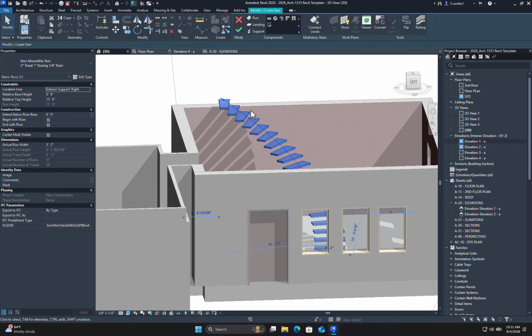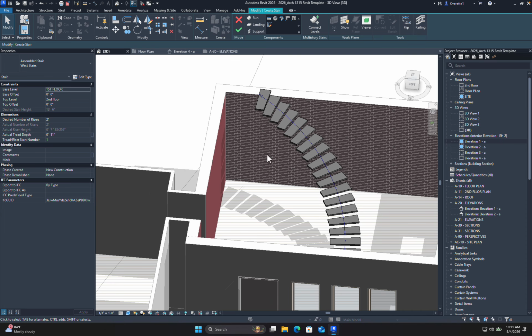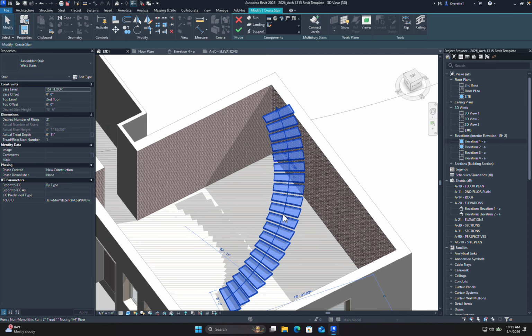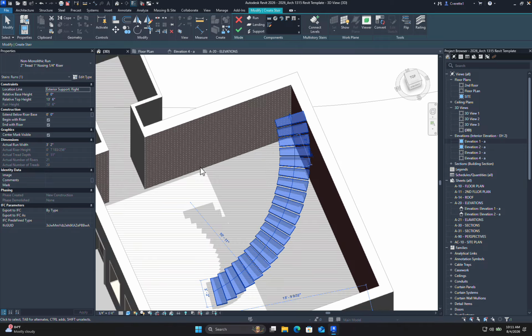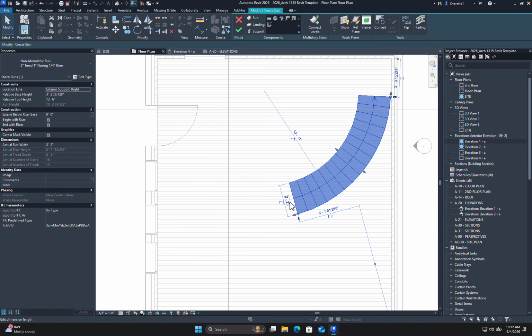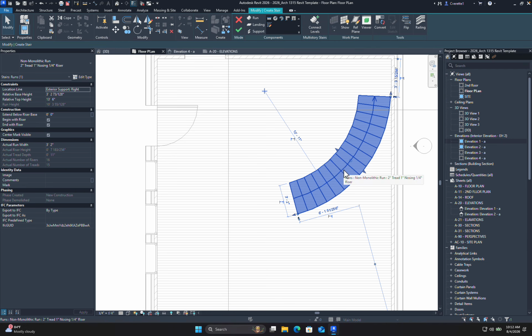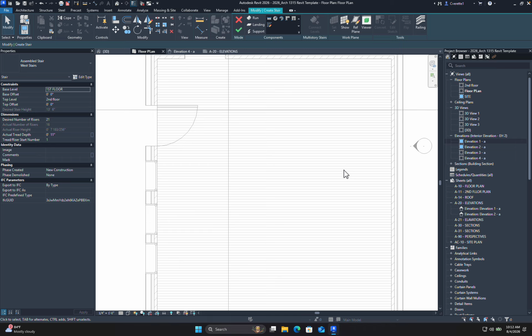If I now double click on these stairs, right, we'll see that there is a number of options. In fact, I've loaded some stairs for us, just like any other piece. However, if you double click, it does turn into an edit mode, and I can basically redraw these stairs. However, it's easier said than done, because as you can see, now I'm basically at the whim of these control points in order to do something, and Revit doesn't like that. Honestly, I usually delete the stairs if I mess up and just try again, right, to be completely honest with you.